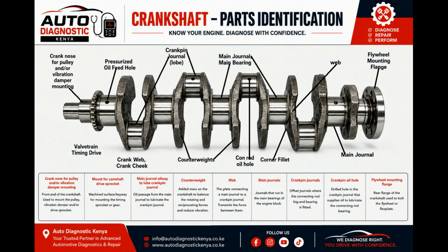The spigot bearing. And now let's connect the crankshaft to the gearbox. The engine produces power, the crankshaft rotates, and eventually the power needs to reach the transmission. And the connection is through the clutch. The gearbox has an input shaft. The shaft is supported inside the gearbox, but what about its front end? It also needs support. So that is why the spigot bearing comes in.